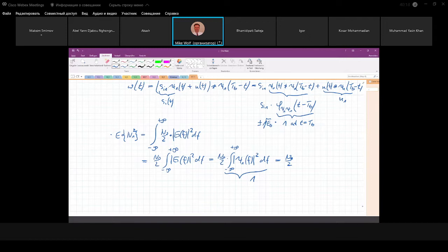If you want to realize something and you have a filter, and your signal bandwidth increases, so the bit interval decreases, you transmit at a higher bit rate, you increase the bandwidth of a real-world filter, and you get more noise. Here you say, I normalize this filter in order to have unit energy, and the noise variance is independent of the bandwidth of the signal because of the normalization. But at the end, we will see we get exactly the same.